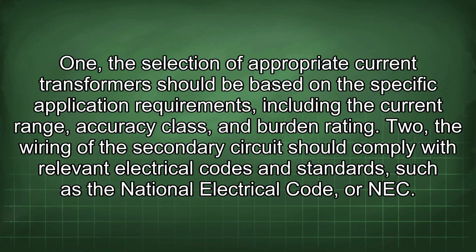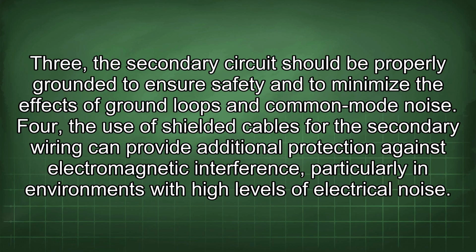class, and burden rating. 2. The wiring of the secondary circuit should comply with relevant electrical codes and standards, such as the National Electrical Code, or NEC. 3. The secondary circuit should be properly grounded to ensure safety and to minimize the effects of ground loops and common mode noise.